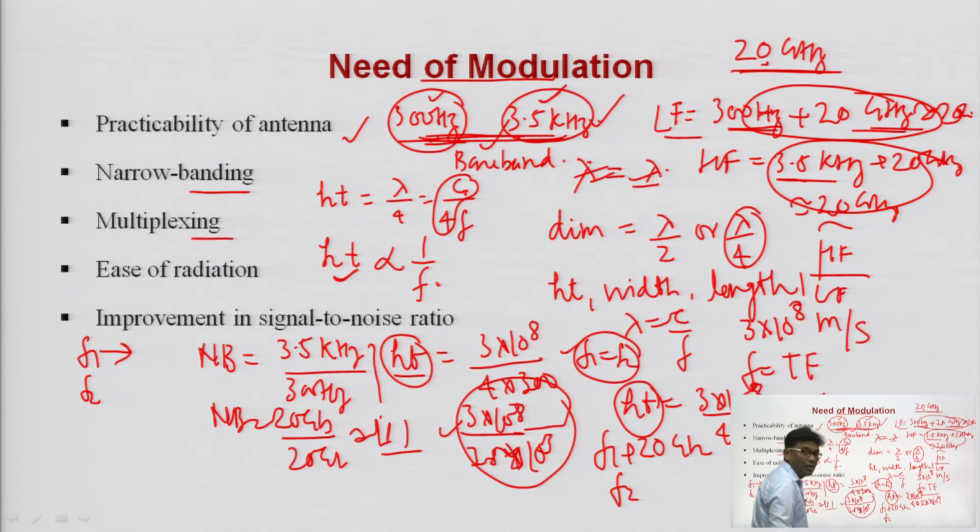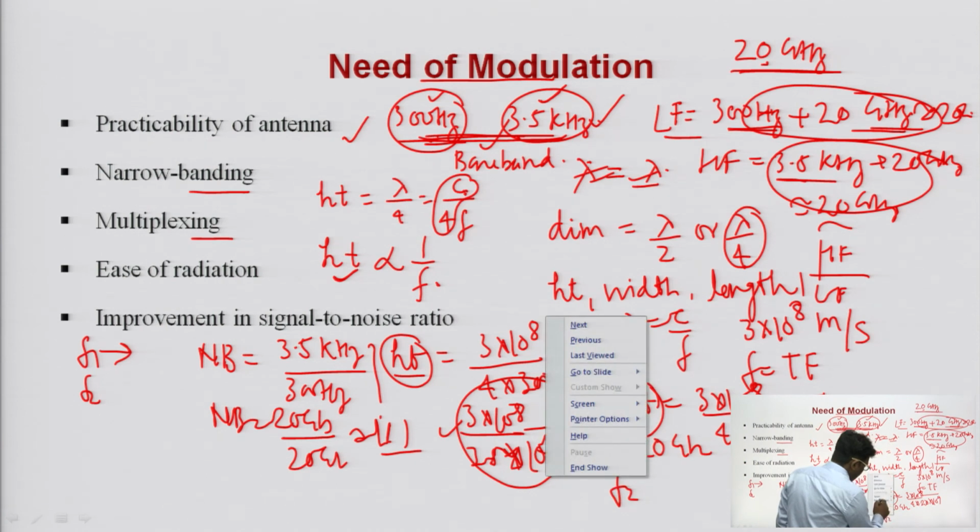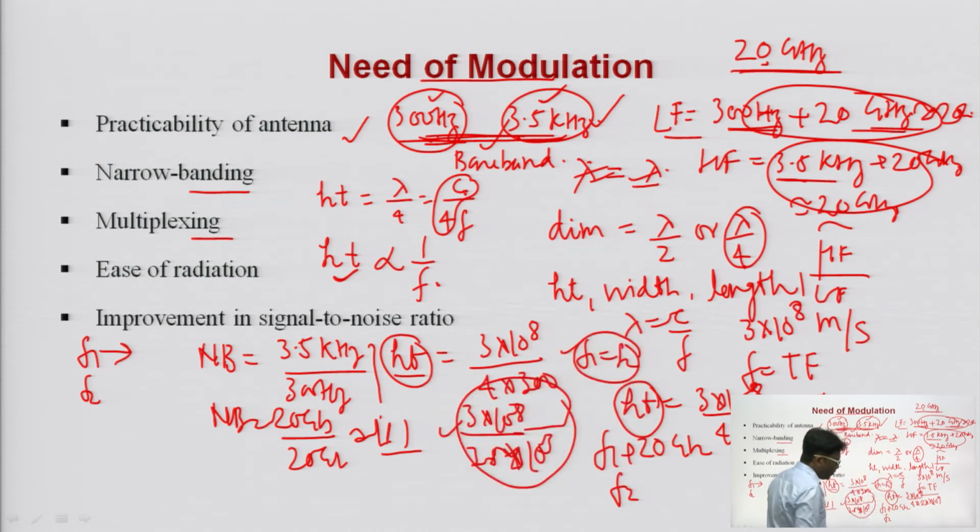It means we have translated the speech of the 2 different students to different frequency ranges, hence they will never overlap when they ask me a question simultaneously. So, multiplexing is the process in which we shift different baseband information into different frequency ranges so that they cannot mix with each other.